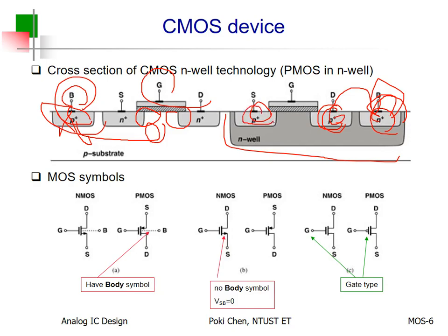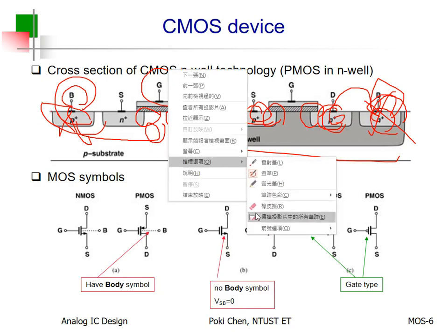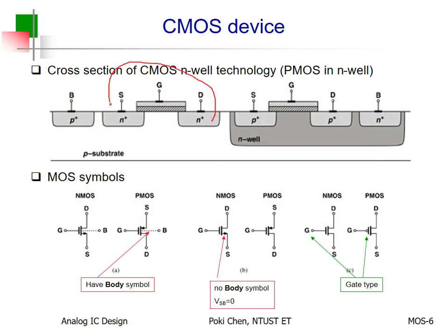That is the key for fabrication. And why? I told you already. Because we need parasitic diode here, diode there, but no parasitic diode for our body contact. Keep this in mind. If you are a circuit designer and would like to design a circuit, you need to draw such a very complicated cross-sectional view. Oh, that is too hard.